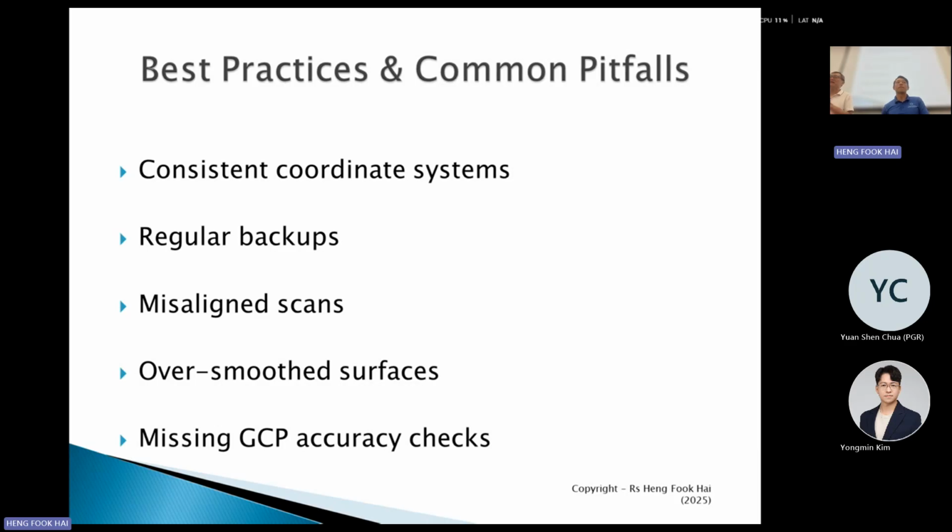And you are unable to see them. So as I said, we also try not to over-smooth the surface, because as engineers, the terrain is the most critical part in your design, right? Smooth it too much, then it will not depict the actual condition of the site.